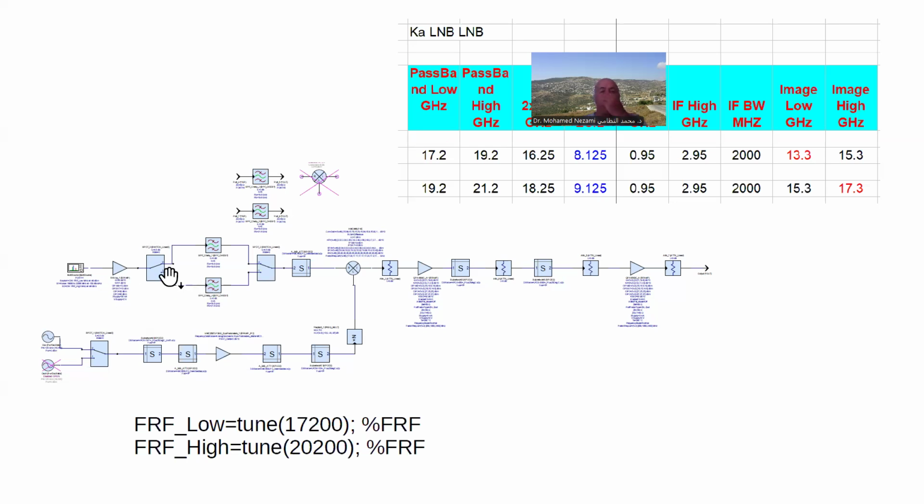I go through a switch in here that switches between these two filters. And then, of course, you switch these signals back into a MMIC bipad attenuator that will be used to basically improve the isolation and return loss to the mixer. I go into the mixer, and then from the mixer, I have an IF section, which is made up of two filters that I will tell you about in a moment, and then two identical MMIC amplifiers.